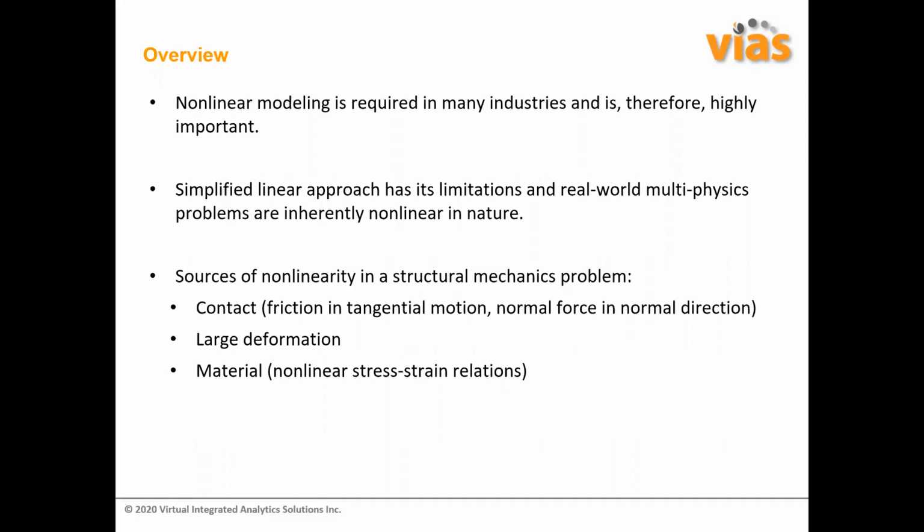From a strict structural mechanics point of view, there are three main sources of nonlinearity present in a structural mechanics problem. First, contact, either hard contact without friction or with friction. Second, large deformations, such as whenever a structure is undergoing large deformation under the influence of forces or moments, or it undergoes rigid body motion. And third, material nonlinearity, which basically means nonlinear stress-strain relations.